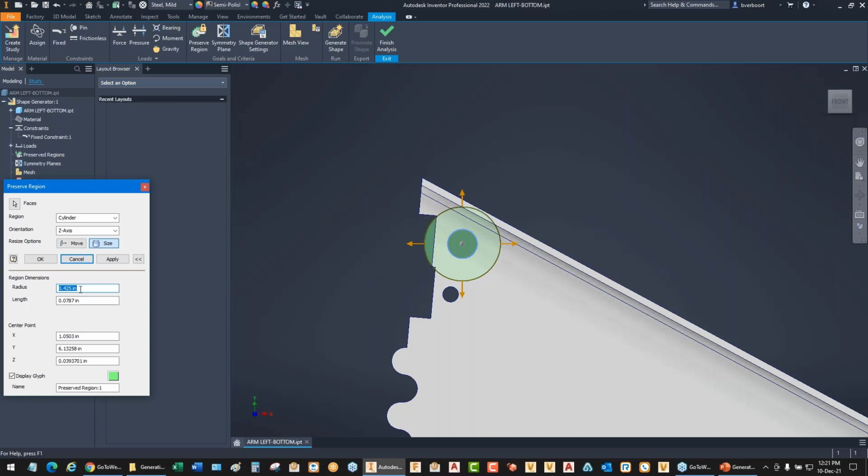This is important because it's not just the hole I want to preserve. I need some bounding surface around the hole for the fastener to bear upon. The hole is a lack of a feature, and we need it to have some, otherwise the bolt will just drop right through if we didn't have a bearing surface.